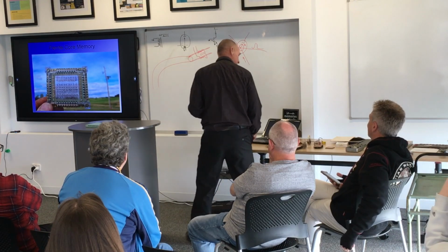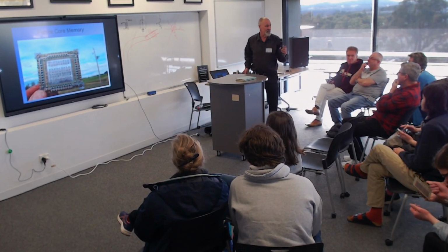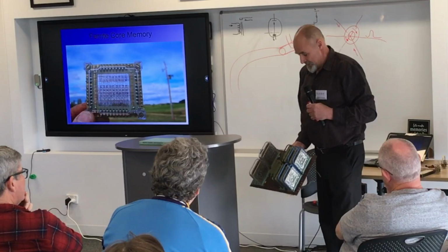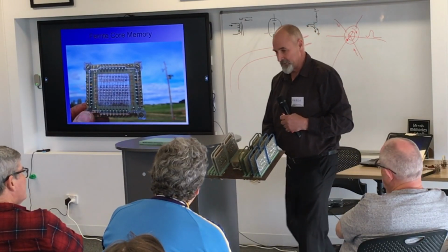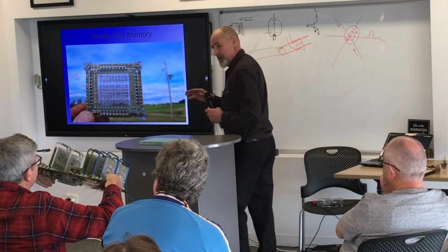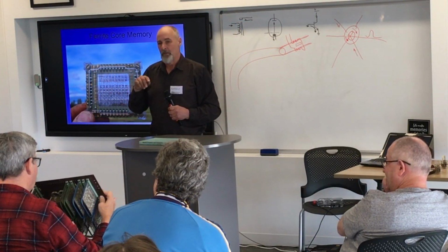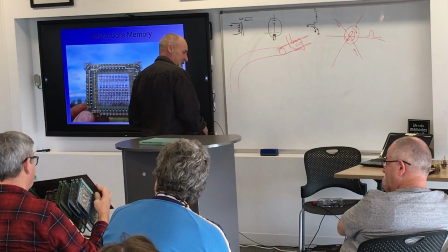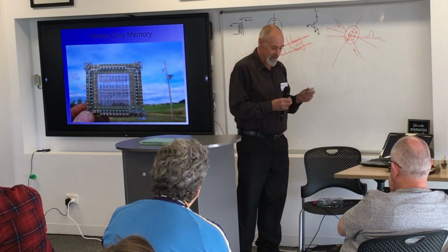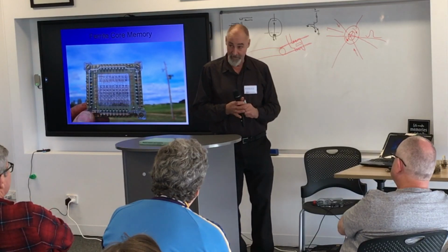So there we go. Now, the GE225 that I've been talking about out there used what's called 3D core memory. This is out of a Control Data, I think. You can pass it around. What they do is make a plane of ferrite beads and then stack them, but they wire another wire into the bead that loops through all of the beads on that plane, and that's called the inhibit.